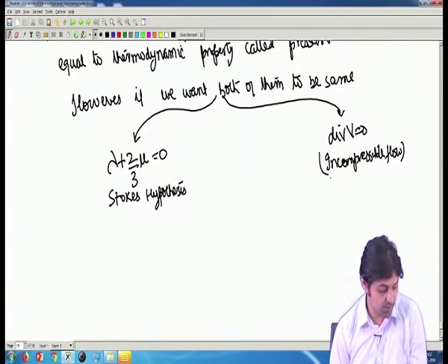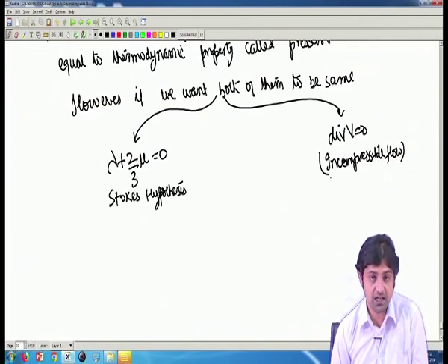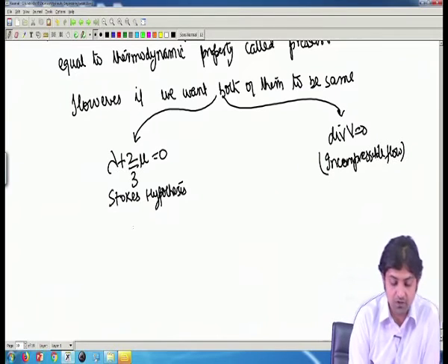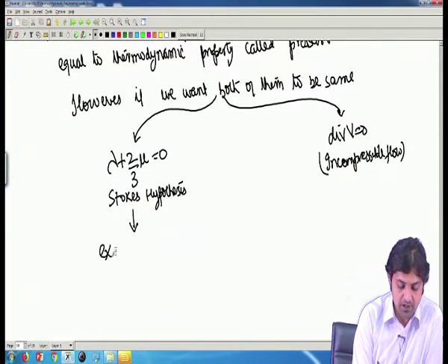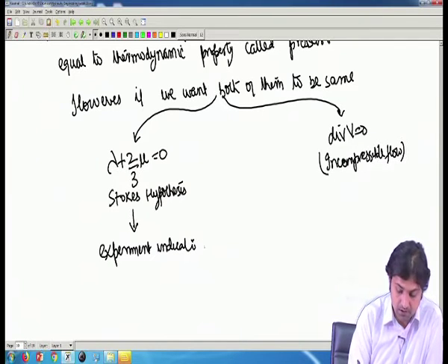Now coming back to the Stokes hypothesis, it says even in case of compressible fluid, if lambda plus 2/3 mu is equal to 0, then we can have them equal. However, experiments indicate that it's rare. So lambda is generally not equal to minus 2/3 mu.